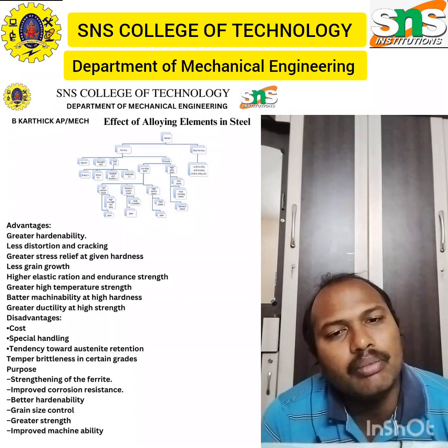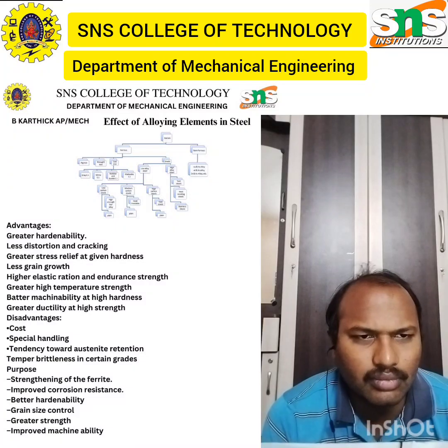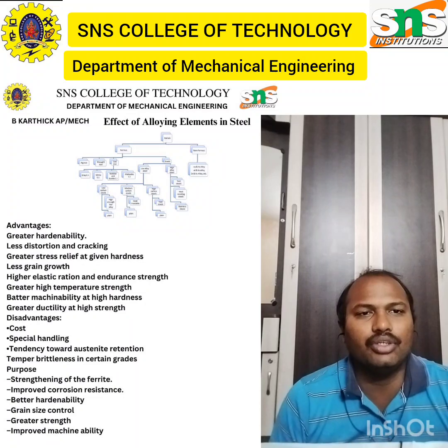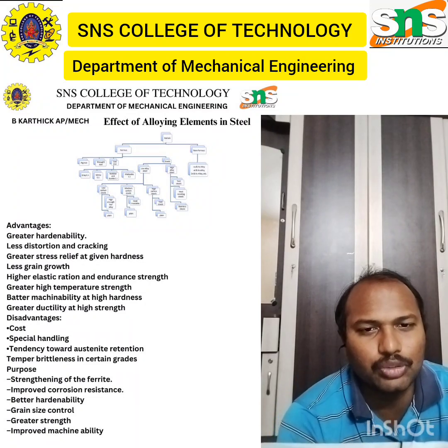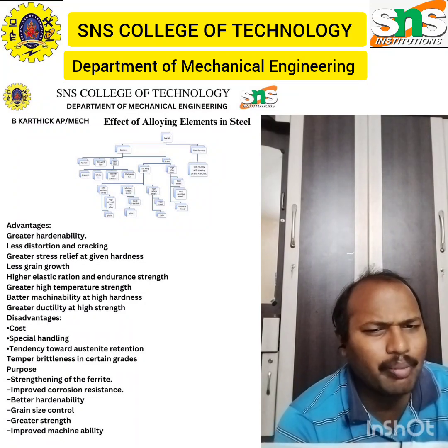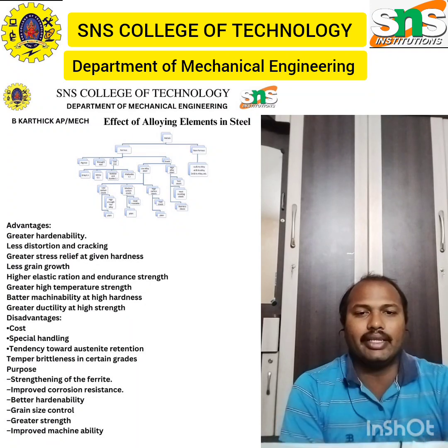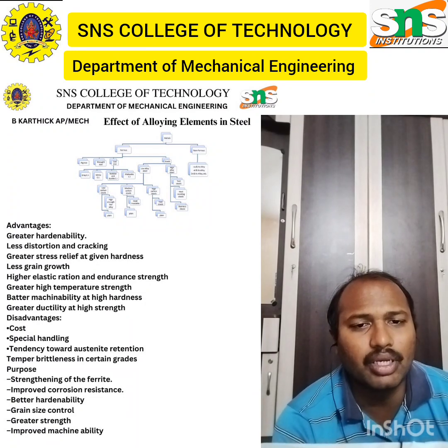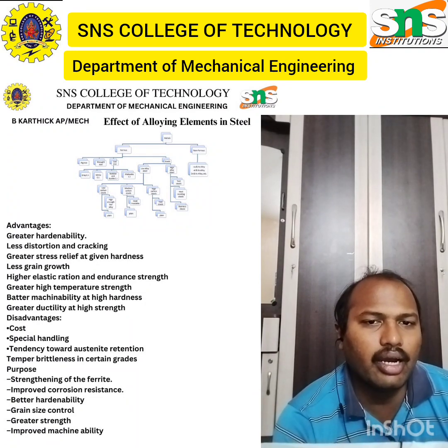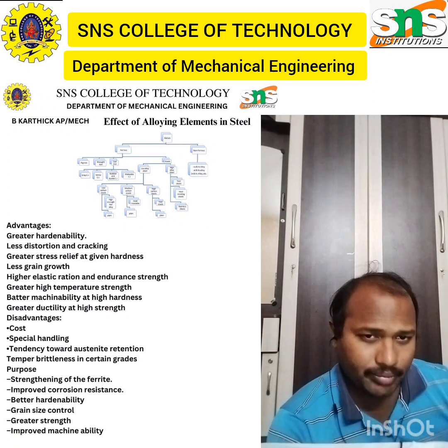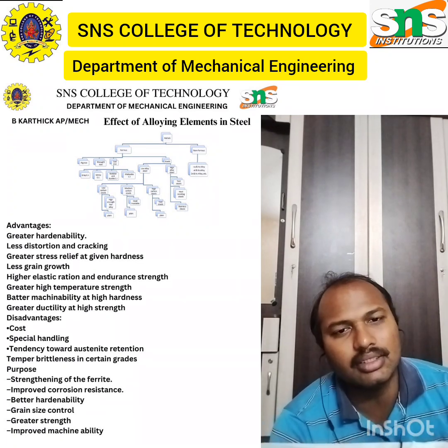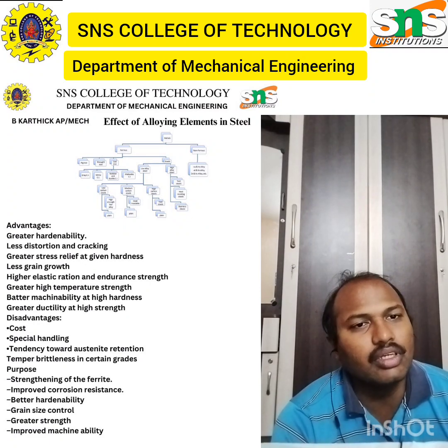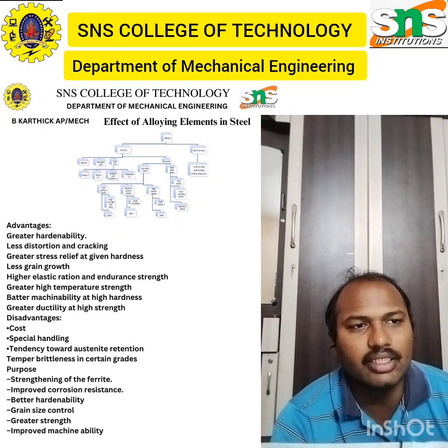Some alloys which are used in many applications or in many steel grades need special handling. Carbon is easily handled, but silicon, manganese or magnesium require some precautionary measures. Grade wise, some temper brittleness may happen in certain grades. And the final part is the tendency towards austenite retention.